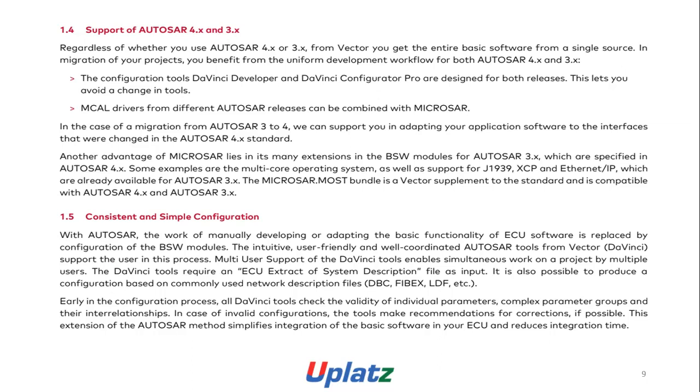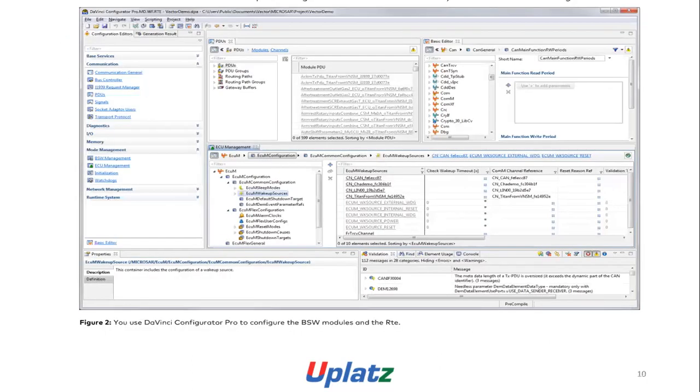Early in the configuration process, all DaVinci tools check the validity of individual parameters, complex parameter groups, and their interrelationships. In case of invalid configuration, the tools make recommendations for corrections if possible. These sections of the AUTOSAR method simplify integration of basic software in your ECU and reduce integration time. Here is how to use DaVinci Configurator to configure BSW modules and the RTE.